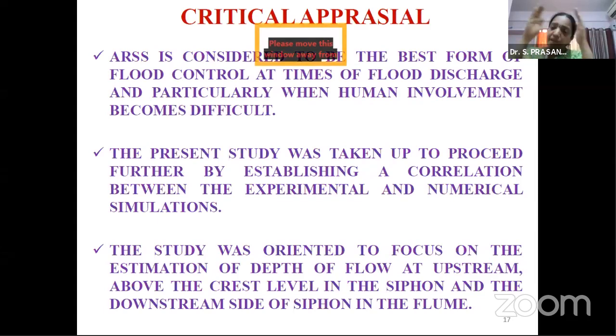In this particular application, dynamic pressure is not a constraint for us. Where we have done spillways, our target was dynamic pressure, because when we look into cavitation, dynamic pressure has to be evaluated for spillways.